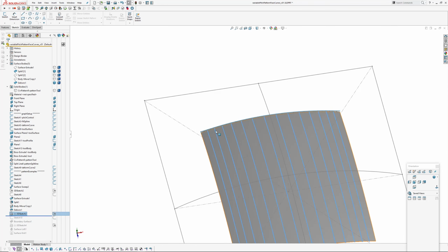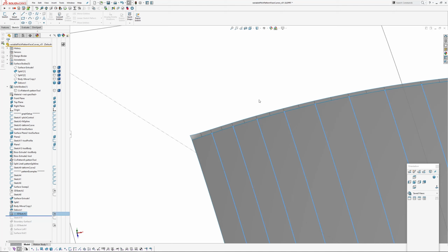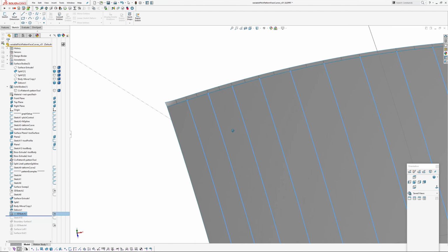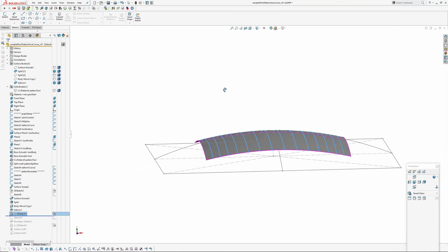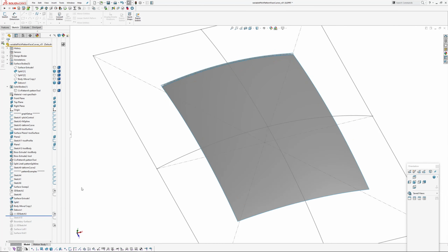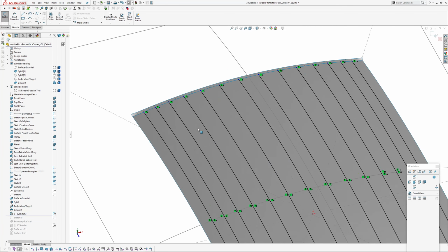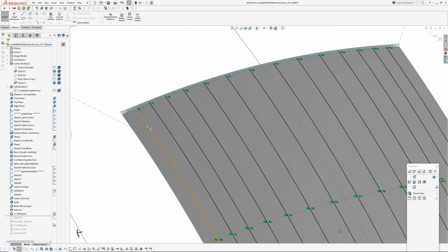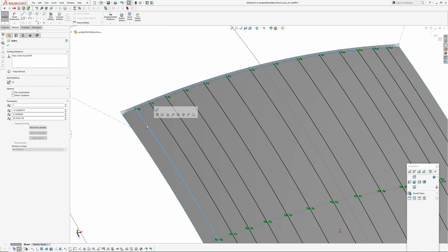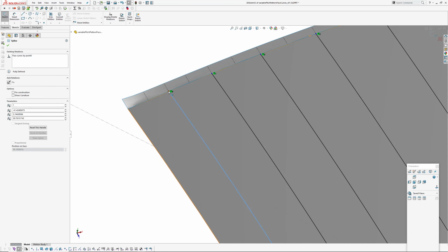Because we've got ripples, I'm basically going to go up, down, up, down, up, down. So I'm going to pick every second segment on my tool body there, and they're going to lie on this surface. In this case, because I've decided I was going to use face curves, each of these curves is a face curve that is coincident to a point here.